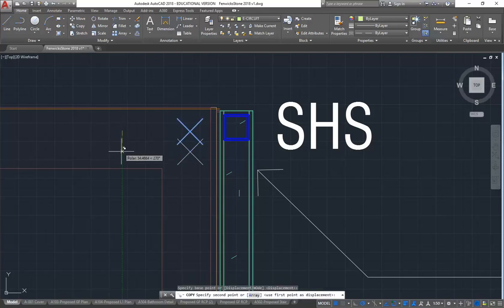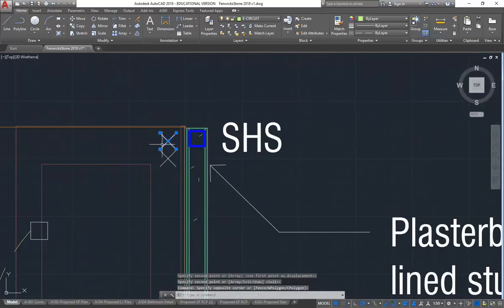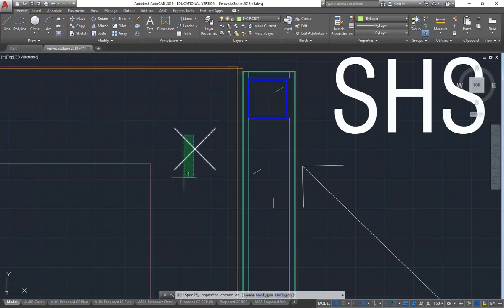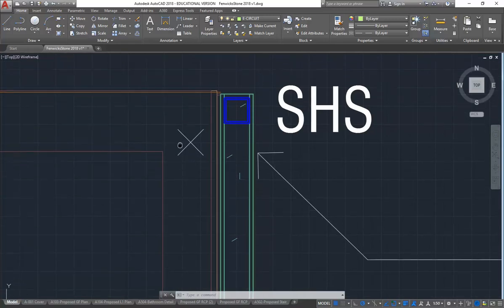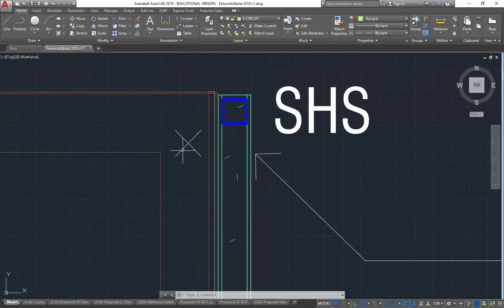You can, that's an option. If you put a number in millimetres, you can specify that. For CC drawings, which is really what we're doing, that's not necessary. That's something you'd do more with working drawings. So here, no, it's not required. And do we put dimensions from the corner, or no? Electricians can work that out on site usually, as long as you're given a rough location. It's probably better not to be too precise. If you're not totally familiar with all the construction requirements, you can actually get into trouble when you put too many dimensions on and they're wrong.